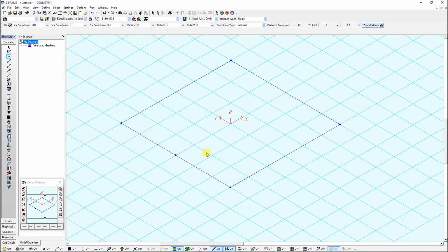Next step will be to copy this joint into the clipboard and generate a first copy around the Z axis, because I want the circle to be in the XY plane. Since my circle is going to be 360 degrees, I'm planning to generate copies every 10 degrees and also include some members. In total, I will have 36 members that will define my circle.